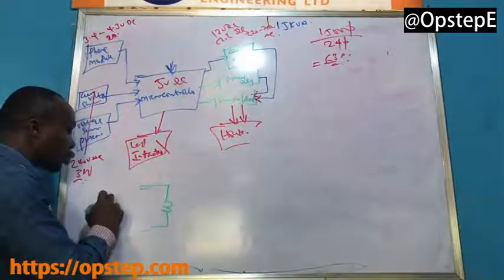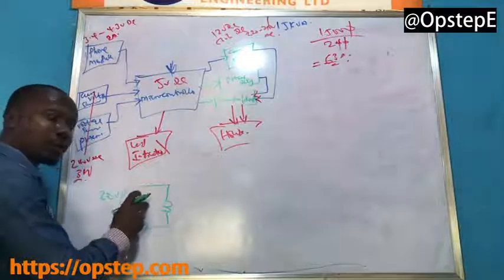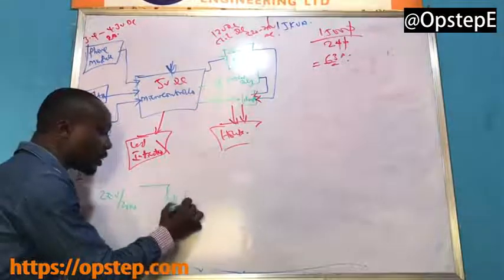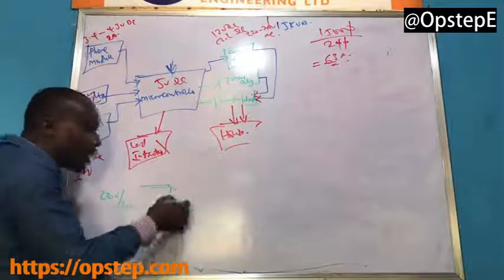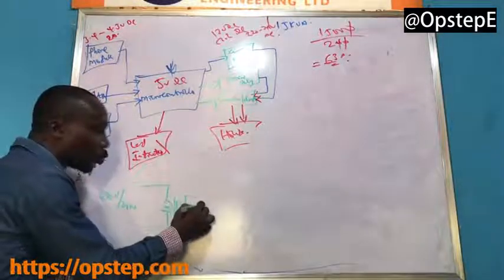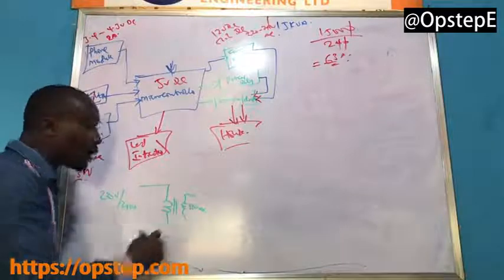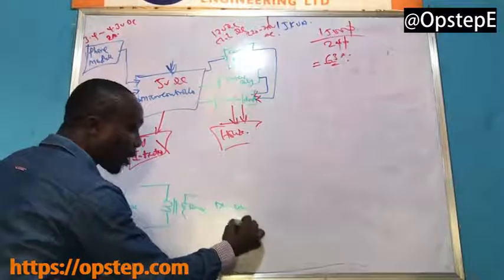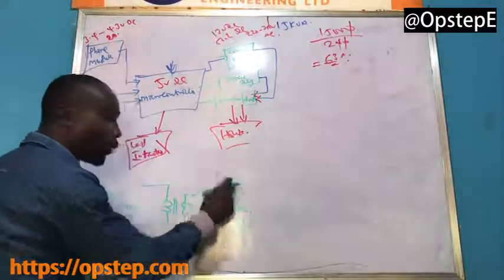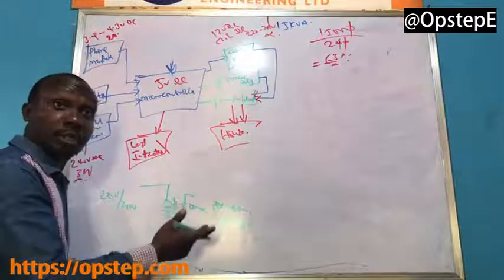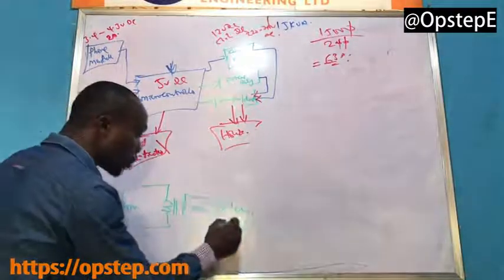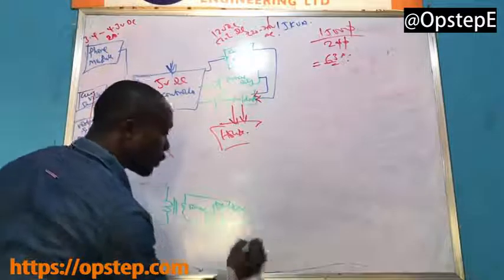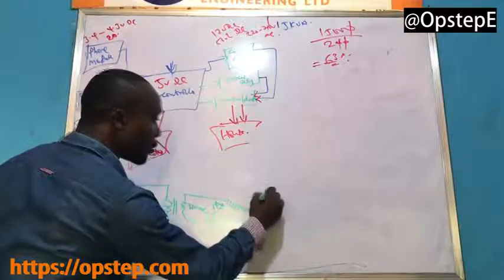Don't forget the voltage is 220 volts to 240 volts from NEPA or from the generator. We're going to take it into a main step down transformer, a transformer that can step it down to what? To 12 volt AC for us. That voltage is now going to go into a bridge rectifier. 4 rectifying diodes will make a bridge rectifier, such that one goes in, the other goes in. You now have your negative output here and your positive output here.